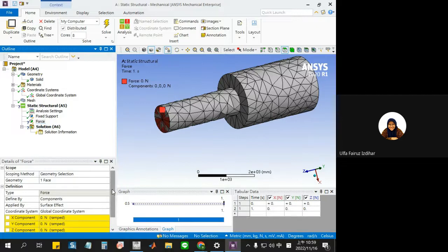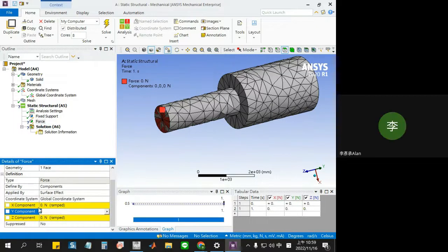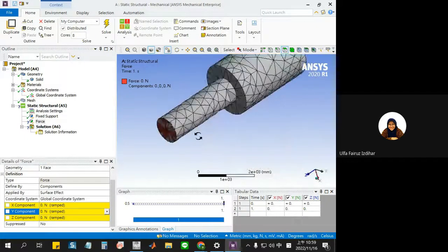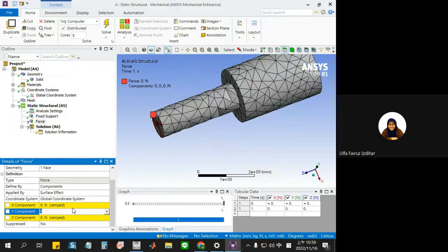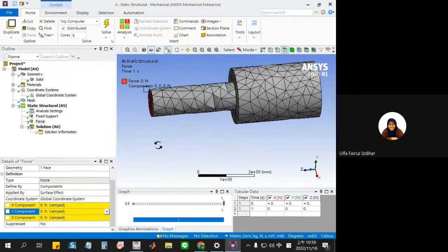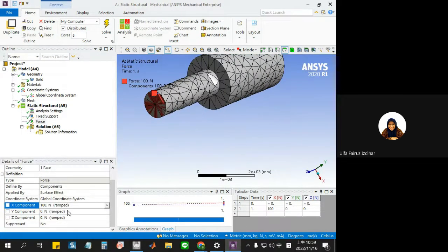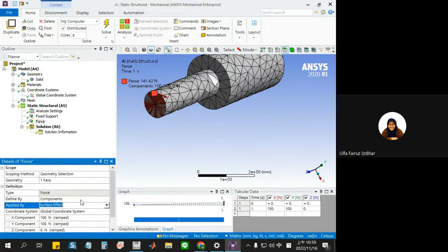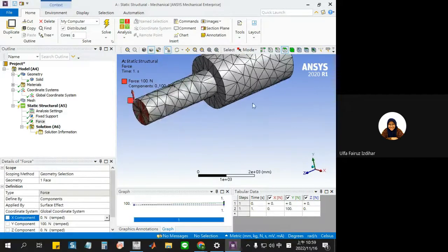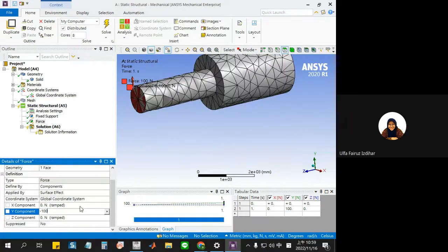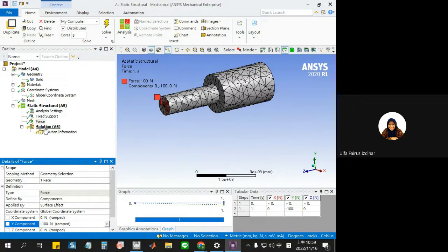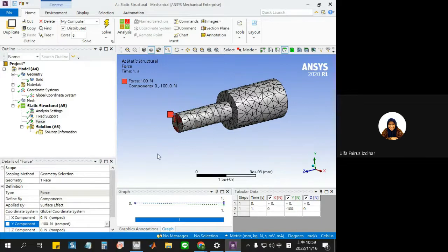Okay, so try to solve it. What force do we need? Oh, you mean what do we want to see? Yes, please show displacement, stress in every direction, and von Mises stress. In the force, just going down, going down. Negative 100 Newton. Okay, good.